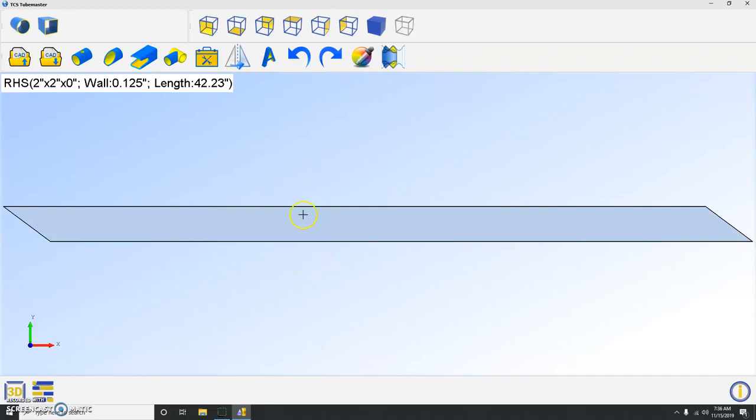From this point, we can add features. We cannot change features that are there. We can't get rid of this miter cut, but we can add circles or holes to it. But again, we can't change the step file. So really, 3D step file input should only be used on parts. I'm not a big fan of doing part of it in CAD and then changing it here. It really should go back to your original CAD program and change your drawing appropriately or accordingly.